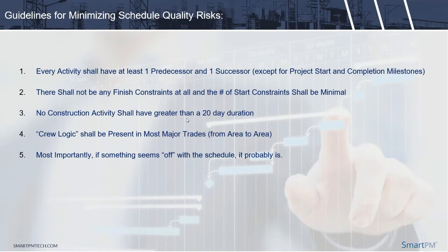I would say that it's important to keep the number of days on a construction activity less than 20 days. That's a month. 20 work days is typically a month. You don't want any more than that, because an activity that generally could be done in 10 days, but you put a month down or 2 months, it could take over the critical path and actually not be critical. I call it hijacking the critical path, just because it's got this really excessive duration and no logic really in the mid parts of that duration, because there's just not enough detail.